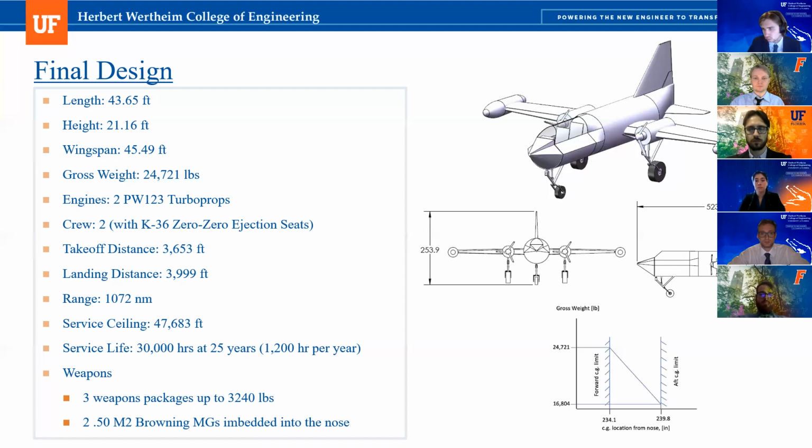Then based on that, I can say that based on the lift-drag ratio, the lift coefficient required at takeoff and landing, the lift coefficient required at cruise, and the wing loading and everything, we use that to guide our design. So what is the wing design? Why do you choose this airfoil? Why do you have this taper ratio, dihedral, everything? And then for the wing design, at the end, for a completely designed wing, we have a performance analysis.